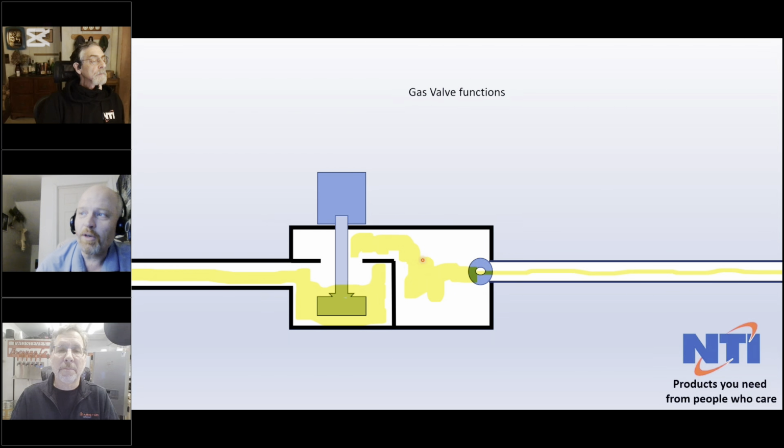Unfortunately, in this scenario, we still run into the same issue, which is that even with an orifice there, the outgoing gas pressure is 100% directly tied to the incoming gas pressure, which, if all of your propane regulators out there are working perfectly, that's not a problem. But we all know that those conditions don't really exist.